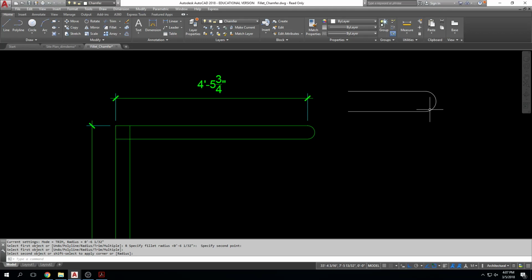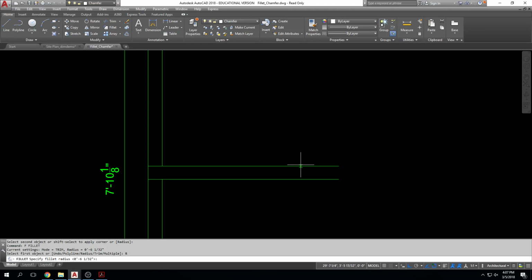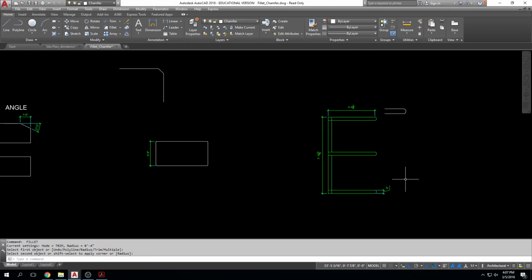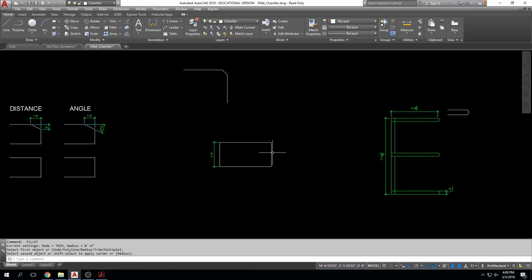Okay. So F for fillet, enter. R for radius, or click on radius, specify the radius, right? I can enter a dimension, but I can also click between 2 objects. Click, click, and that just measured it, right? Enter, click, there we go, enter, and it remembers that operation. By far and away, the radius with a fillet is great, okay? I can create these rounded corners.